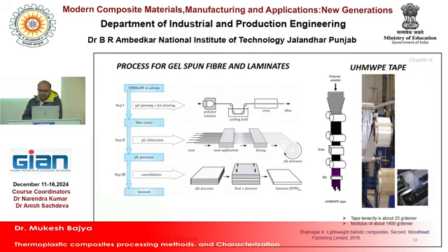This is the precursor material, and this bunch of filaments, you can say yarn, is passed through the resin, and after that it goes through drying, and then you make the ply. You can say this is the precursor material. The resin you are using is thermoplastic in nature, and generally a PU based, polyurethane based thermoplastic polymer is used as the resin.